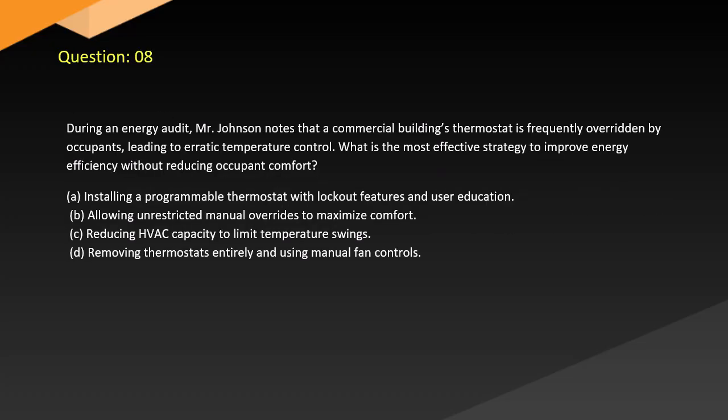Question 8. During an energy audit, Johnson notes that a commercial building's thermostat is frequently overridden by occupants, leading to erratic temperature control. What is the most effective strategy to improve energy efficiency without reducing occupant comfort? A. Installing programmable thermostats with lockout features and user education. B. Allowing unrestricted manual overrides to maximize comfort.